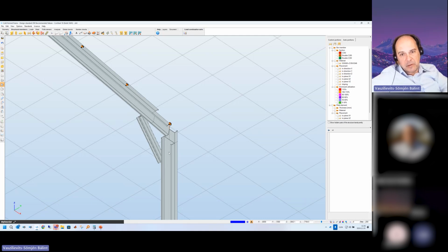You can use special software to make the connection design, or you can find a structural configuration that is more easily understood, such as a typical solution where the bending moment transfer is not directly created between the column and the beam member, but an additional diagonal element is used, and the connection between the column and the member can even be a pinned connection.